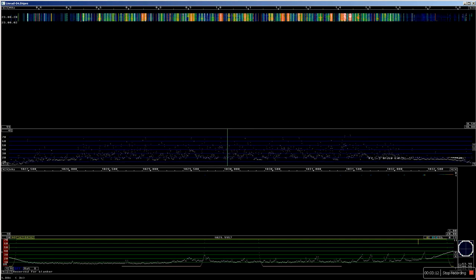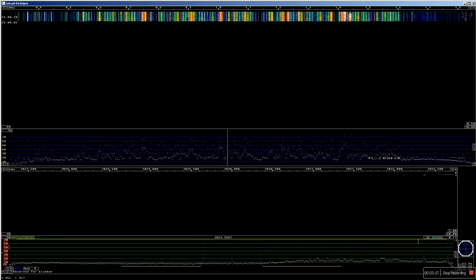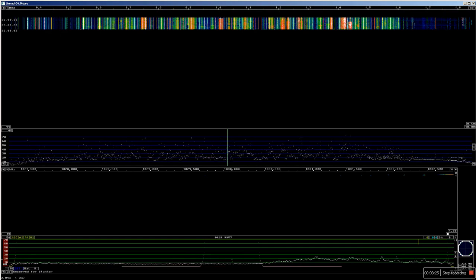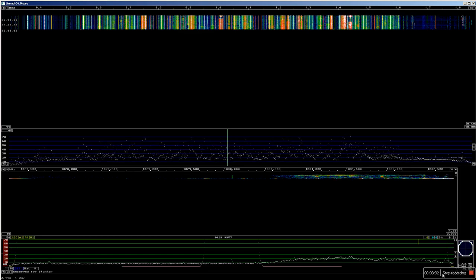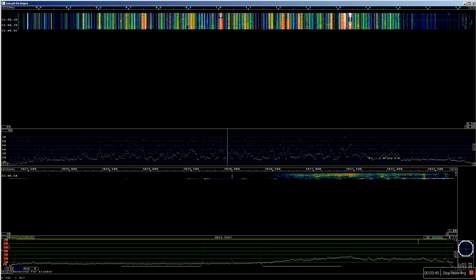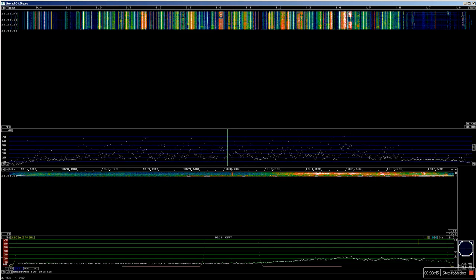and now with the very large transforms the noise floor goes down, so I have to increase the gain, decrease the 0 point of the baseband color scale. I can try 0 for example, yes. And here we can see there is a carrier on 1030, and for all I know it is probably an American station. I put minus 10 dB here, so we can see it in the noise.